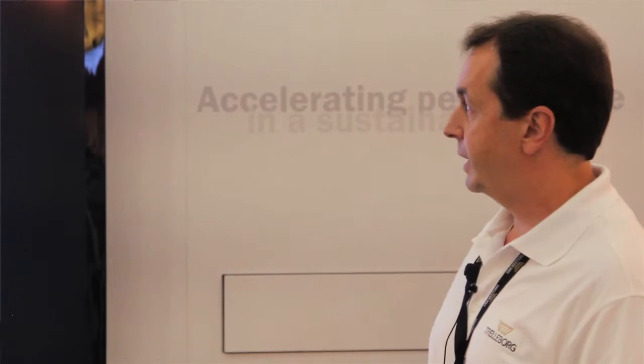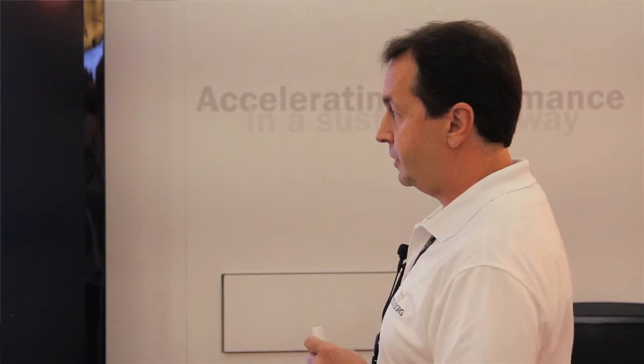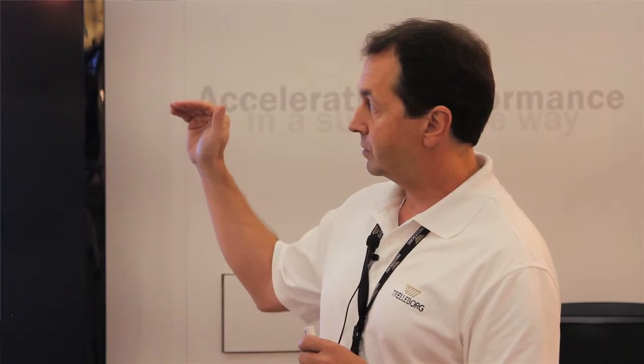So to give an example of this, here's a simple 2D analysis of a spring-energized seal, which for Trelleborg Sealing Solutions we call a VeriSeal, with the orange product being a backup ring. As you can see, we simulate the seal being installed. The top plate is coming down, compressing the seal into the groove, allowing it to seat. And in a second here, we'll subject the seal to temperature, which will cause the seal to expand. And after that, we will subject the seal to pressure.